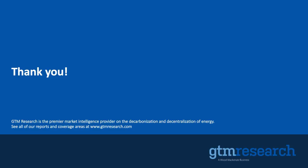Let me start with the fleet DERMS or virtual power plant side of things. Largely what we're seeing with many of our clients is they're doing that as a direct connection to the assets. So there's always some integration with the assets themselves. Again, we try and use a lot of open standard APIs. We publish some. There's some in the industry. You have to work through a bit of integration to the asset side. The back end system, so the actual software connection between that and, say, the dispatch signal, again, there's usually only 2 or 3 of those signals that come in.